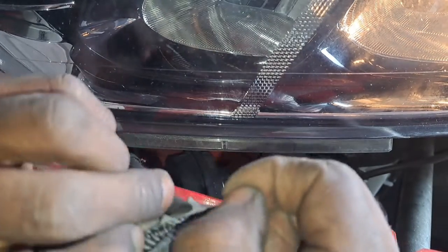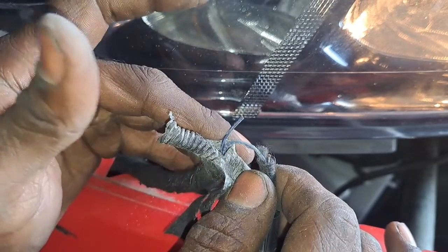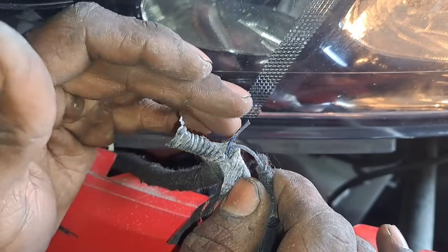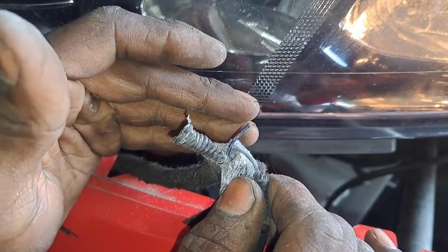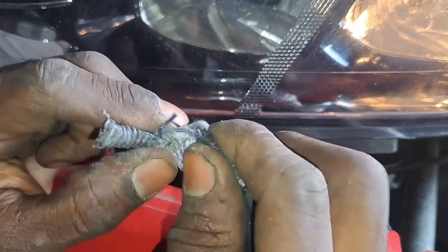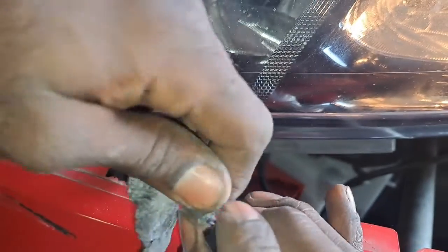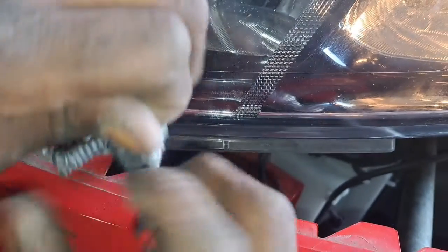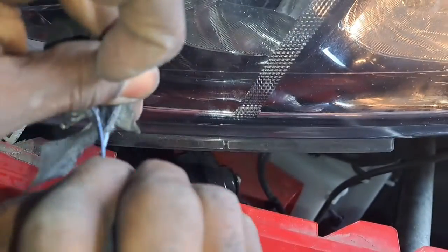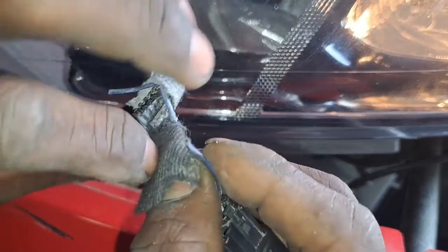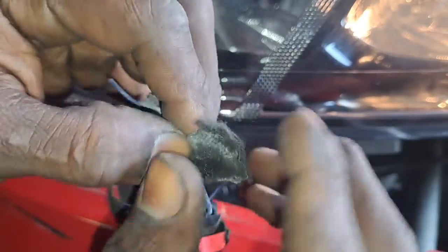But then again, we still wouldn't have been able to discover this without bidirectional scan tools. You couldn't see this in the computer system. You would have to literally go inside the HVAC module, and it wasn't even in there. It was in the instrument cluster. That's where this code was. So simply put, we just need to fix this wire. I'm not even going to back test it. I'm just going to repair this wire, put this back, and plug this joker in, and we're going to see if the AC works. Clear the code and see if it works.